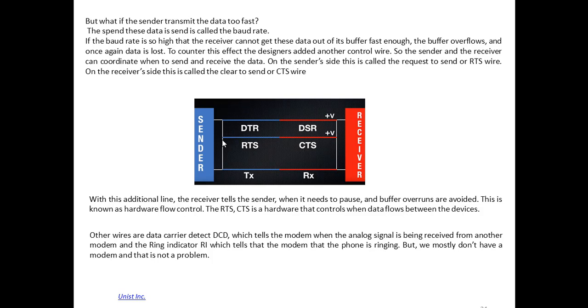So if your instrument can have all these wires connected, then you can bring the chance of error as low as possible. Make sure when you're connecting your instrument to your computer that all these pins are connected. This can easily be done with an RS-232 cable, which already has all the pins.